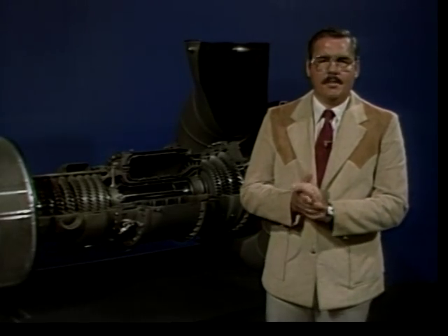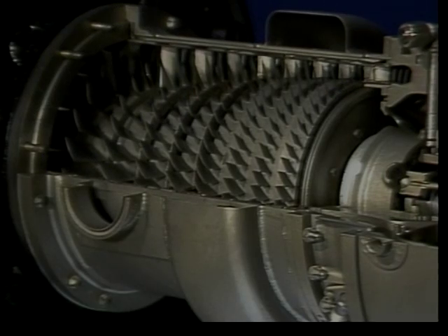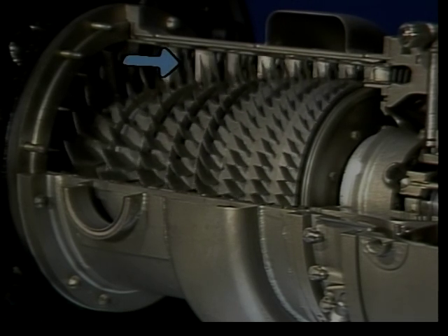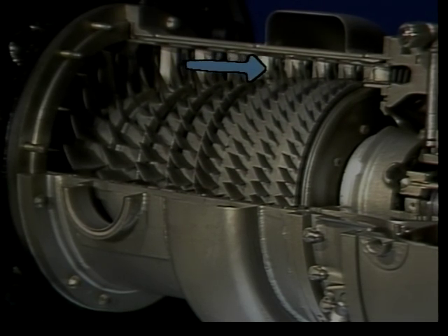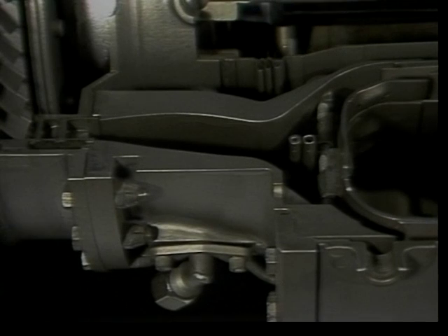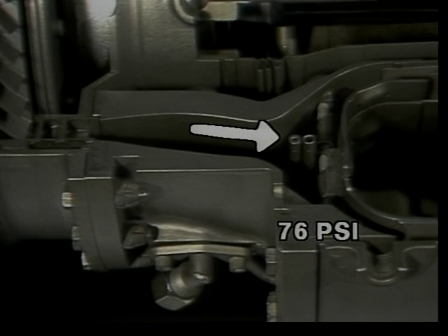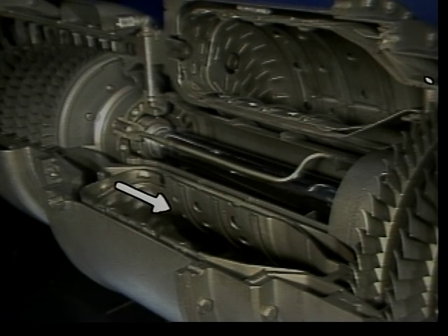To begin the process of energy production, air is first drawn into the compressor. Rows of blades compress the air into an increasingly smaller space. After the air leaves the compressor, it enters the diffuser area. In the diffuser, an additional pressure rise occurs. The pressure at the exit of the diffuser is about 76 pounds per square inch at operational speed and full load, right about here. After the air leaves the diffuser, it enters the combustion chamber where either liquid or gas